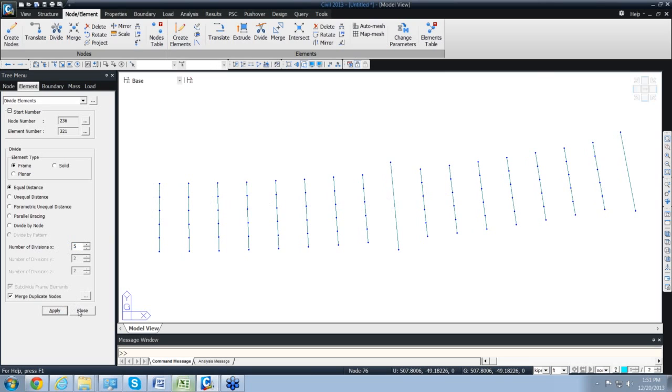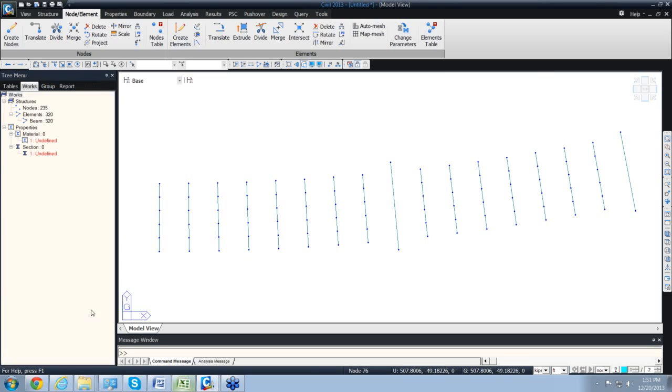So once again, it's something we are supposed to do because we did not have nodes at those locations. If you had an AutoCAD file which had the connection between the transverse and the girder at this location, we would have a node automatically. The reason we do not have the girder here, the curved girder or the node, is because the curved line that you have created in AutoCAD cannot be imported in a finite element analysis software.